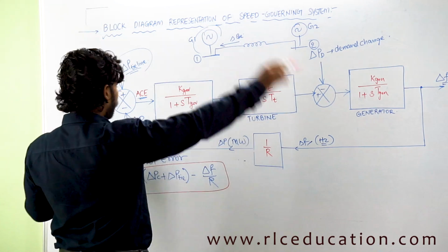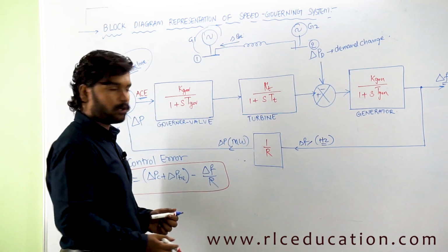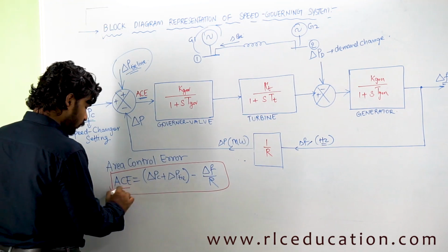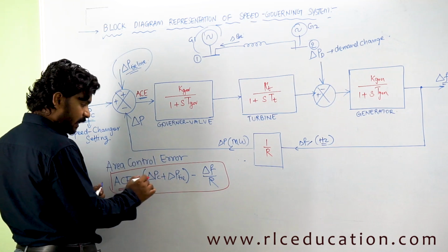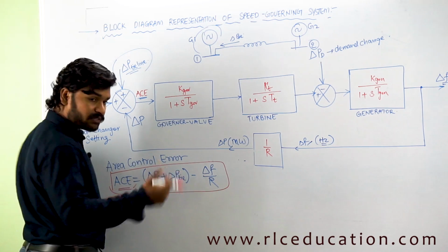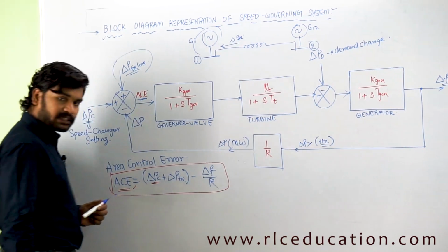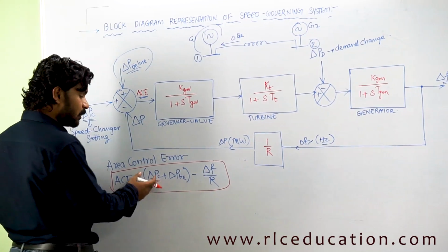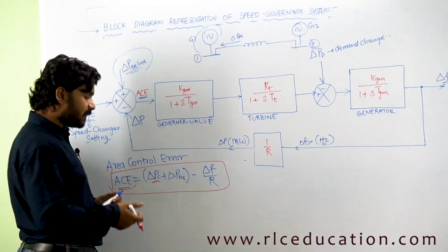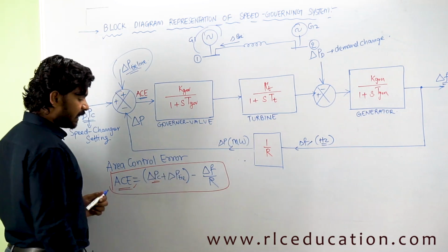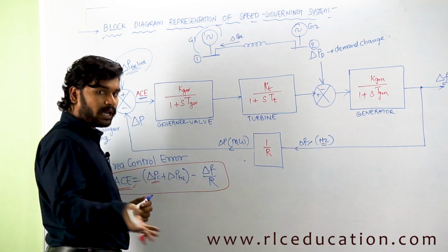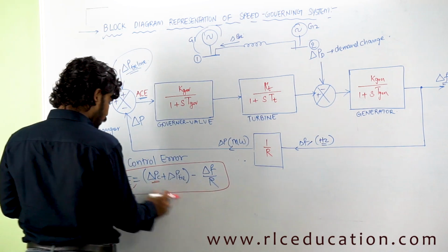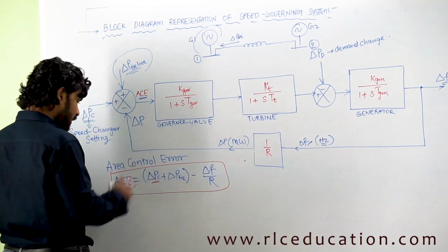Let us say this kind of controlling mechanism is an automatic control mechanism. So how do you basically control? So now you see, area control. Whenever this error has been raised, which one has to be varied, or which one do we have to control? We have to control the speed change setter. Basically what is in our hand is the speed change setter delta PC. If you are varying delta PC only, then only you can vary the frequency. Basically that you have to keep in mind, because delta P tie line, or tie line power, is not in your hand. Tie line power is from the external network, okay. So to control this delta F, you have to control the delta PC, okay. Please keep that in mind.